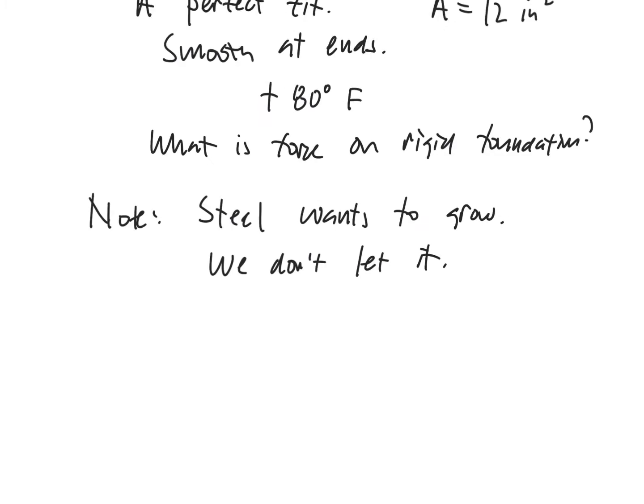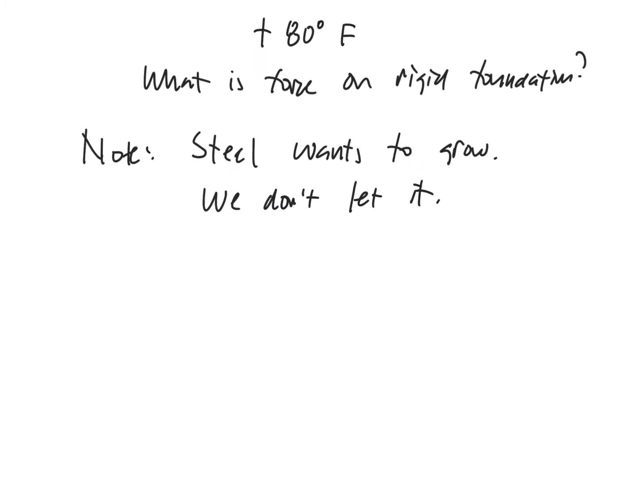Well, now we can use the constitutive law that we introduced just a couple minutes ago, and that is the total strain, what we see and measure, is equal to the stress divided by the modulus of elasticity plus the alpha times delta T. There it is. Total strain, which is what we see and measure, is the stress divided by the modulus of elasticity plus the coefficient of thermal expansion times the change in the temperature.